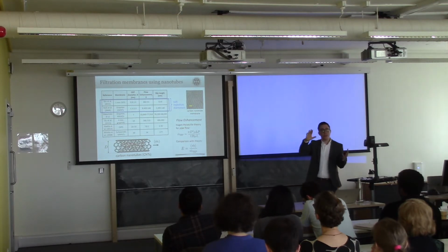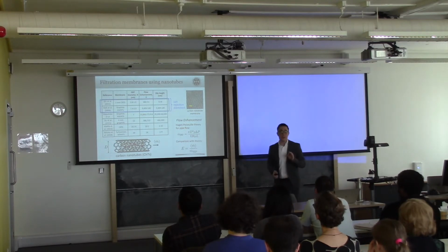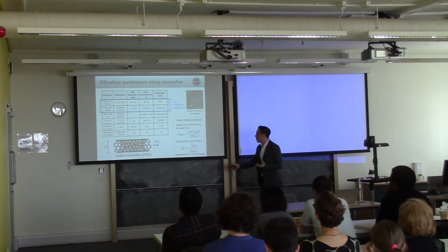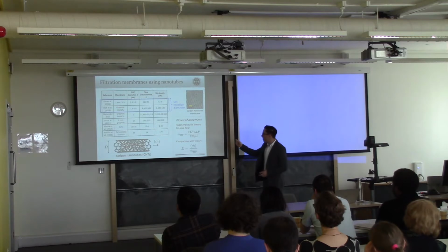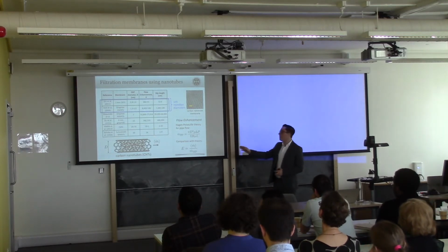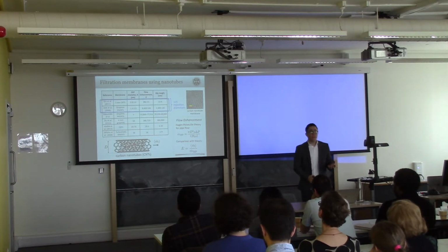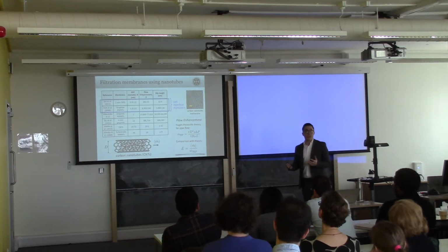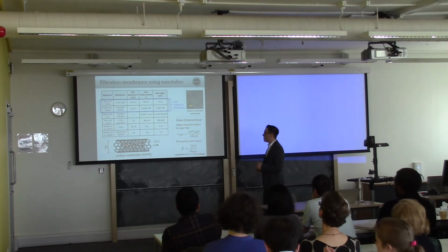Now if we scale that pipe down to a diameter of the order of 1 nanometer, and we observe what that flow rate is, let's say m dot over here. If I define a ratio which is the observed flow rate over what is expected in theory, I get this flow enhancement ratio E. So if E is 1, then our theory predicts everything is great. But if E is much more than 1, then we're seeing some flow enhancement in our system.